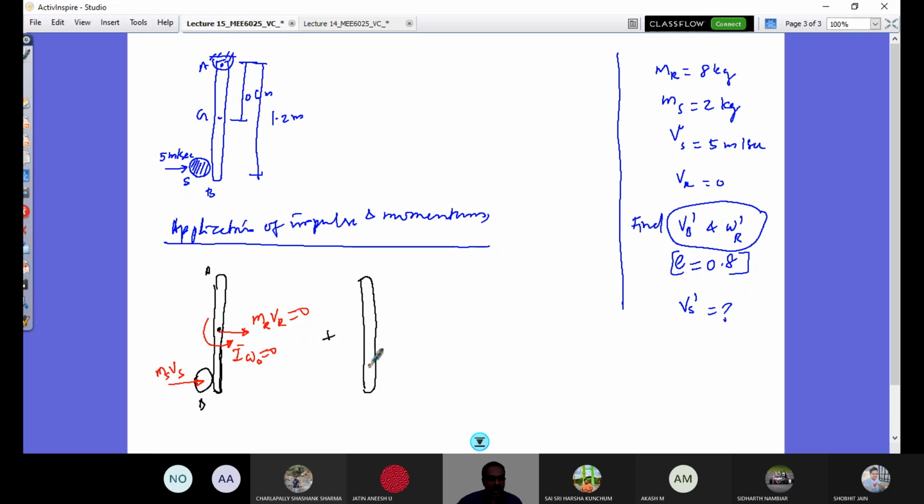So what is the impulse diagram I will have? At this contact, at the end of maximum deformation, or the end of the deformation period, I will have the impulses integral A_x dt and integral A_y dt. And here there is an exchange that gets cancelled. That's why it is not stationary when it hits. You exert the force and the same would be exerted back. I don't draw this here. Instead, I put only the reaction impulses as external.